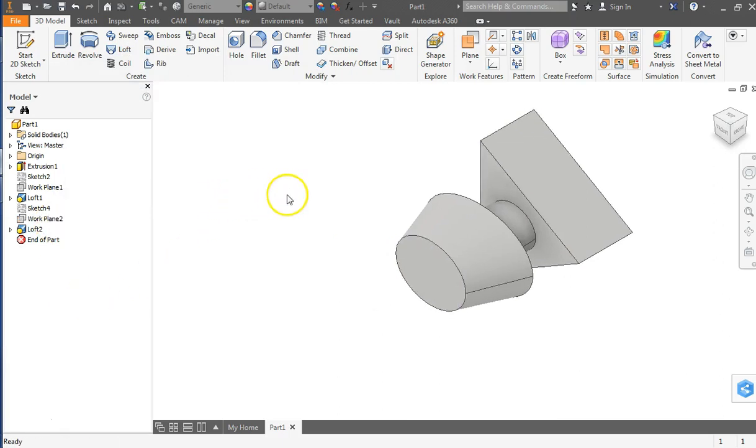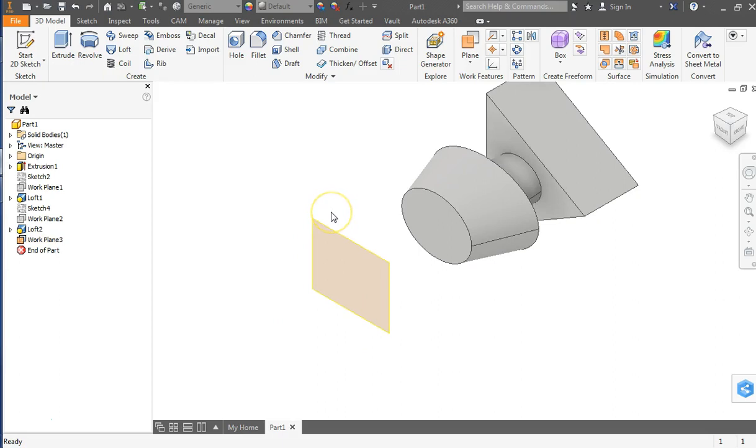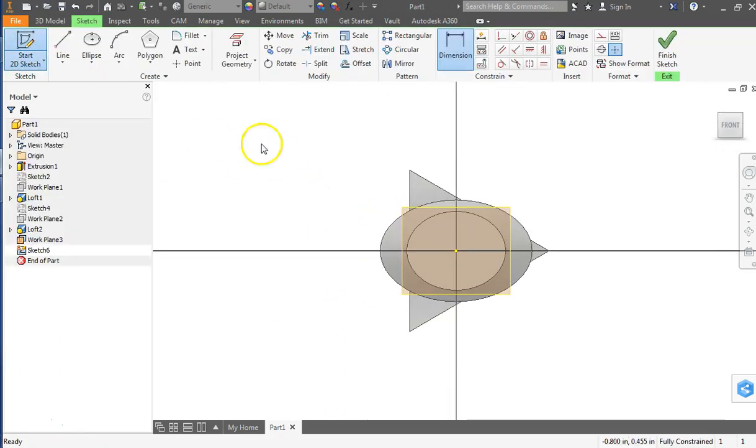And I'm ready to now go from the waist up to the shoulders. So I'm going to go offset from plane. This distance in this direction I measured to be 0.48. So again, very different from my bottom. I had 0.27 and 0.48, so you can see I very much had different dimensions there. Let's start a new sketch on this plane. Again, it will be the ellipse.